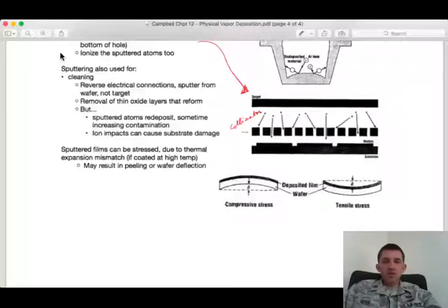And also I could ionize the sputtered atoms, right? So if those atoms are coming off in the region of the plasma, there's a probability that they will be ionized too, which means that they'll have that hook that I need, that electromagnetic attraction to pull those in to the surface, right? So this one goes hand in hand with biasing the wafer.